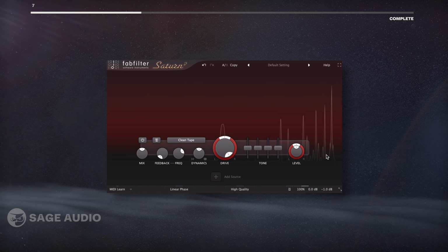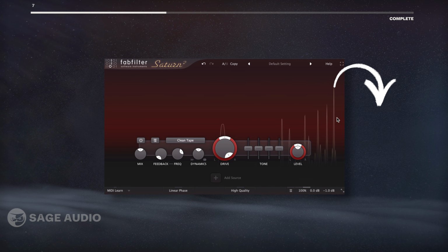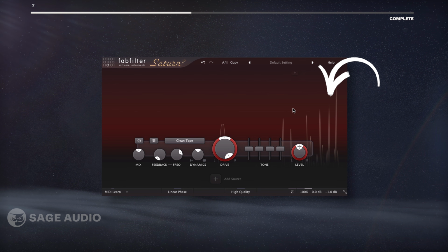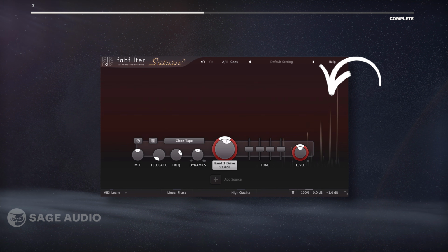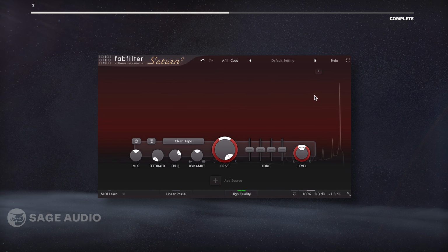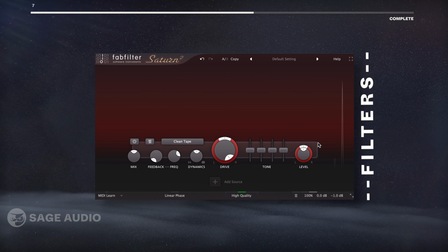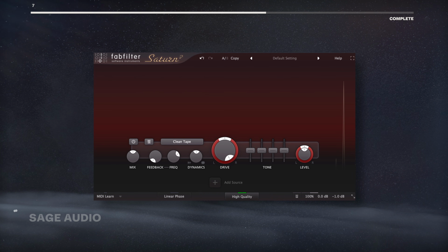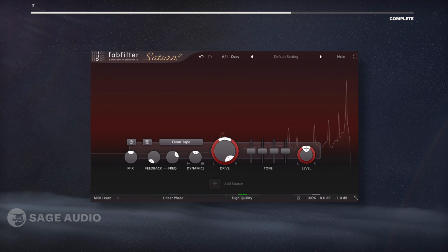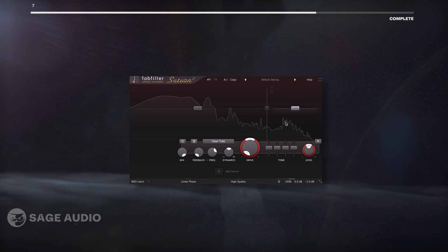If harmonics caused by saturation go above the maximum frequency that your sampling rate supports, they'll get reflected down the spectrum and can cause comb filtering as well as just generally sound unpleasant. Oversampling both increases the max frequency that can be occupied and utilizes filters to attenuate any reflections that may occur. As a result, your emulations sound more like the aliasing-free analog equipment on which they're based. Let's take a listen.